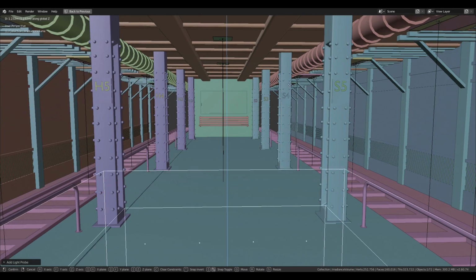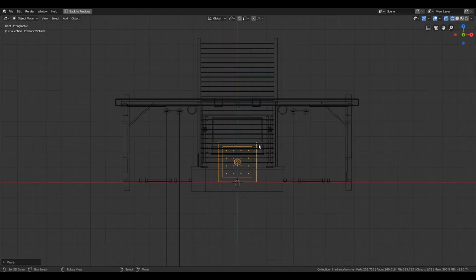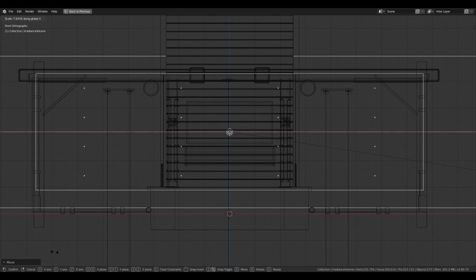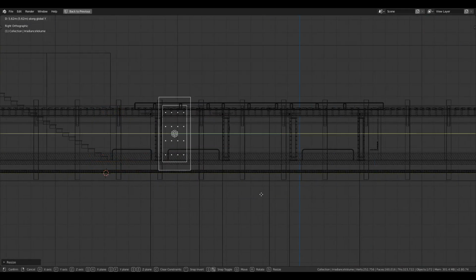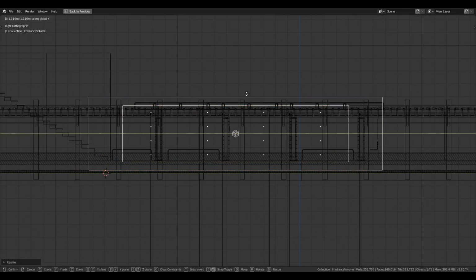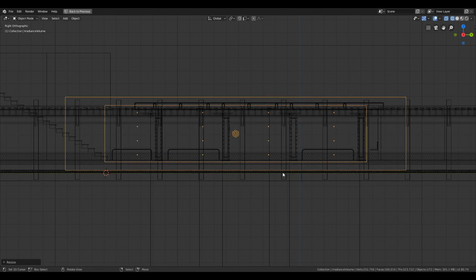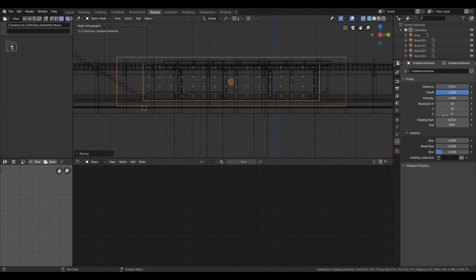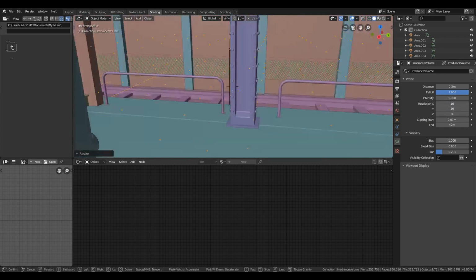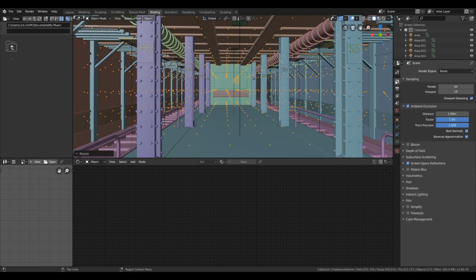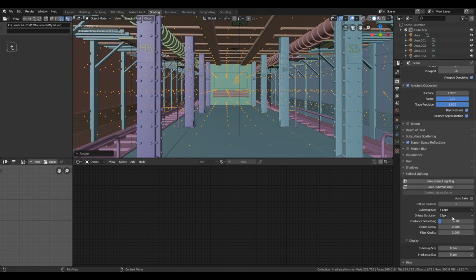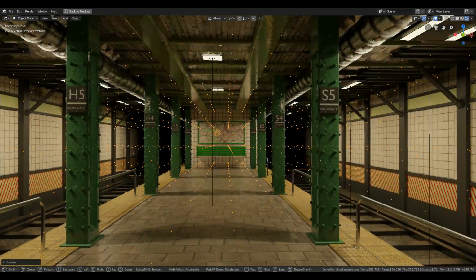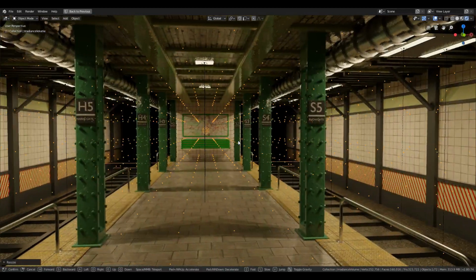For the indirect light, I have used the Irradiance volume, and make sure to cover the walls of the scene with the inner box of the Irradiance volume. Then change the resolution of XY to 16 and leave the Z to 4. After that, just go to the scene tab and hit the bake lighting. You can preview the irradiance size by clicking the eye icon that is available under the baking tab.